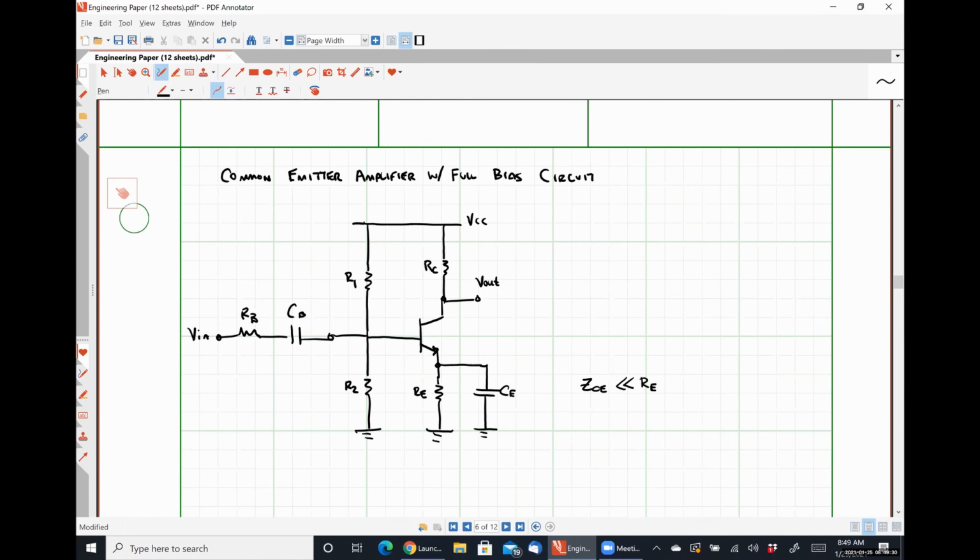What that capacitor CB does is it isolates the signal of the microphone or whatever our sensor is from influencing the bias point of our circuit. So when we're doing our DC large signal calculations, that's an open circuit there, and we don't see that AC input signal causing our operating point to fluctuate.